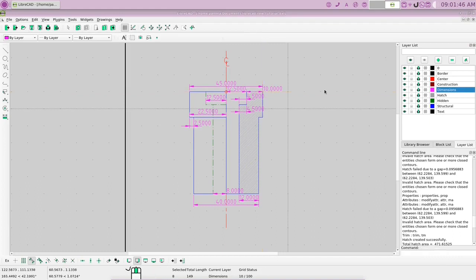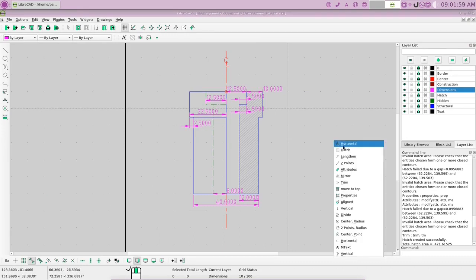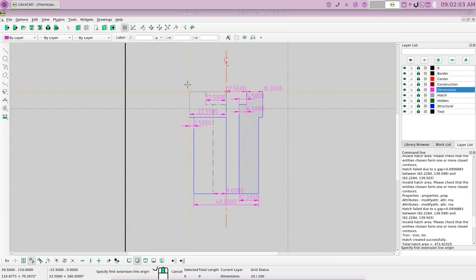So let's get rid of our dimension tool. Let's click on that one and let's hit the delete key. Get rid of it. I want to move it a bit. Let's right mouse click, choose your horizontal dimensions again. Snap on end, snap there, and come up. Take the snap off, move up a little higher. Give yourself a little more room here so it's not crowded.